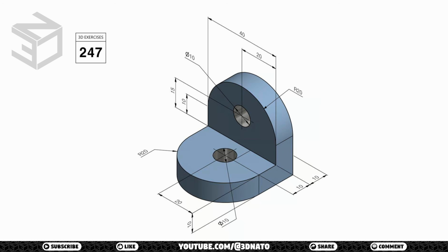On the top sketch, I can see that we have a 20mm radius arc with a 10mm diameter hole in the center. And from the arc to the end, we have two more distances, 10mm to reach the front mesh and another 10mm from the mesh thickness. The front sketch is almost identical. Here the 10mm circle is offset by 5mm from the arc center point. With that in mind, let's make it.